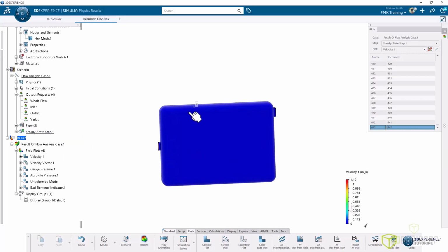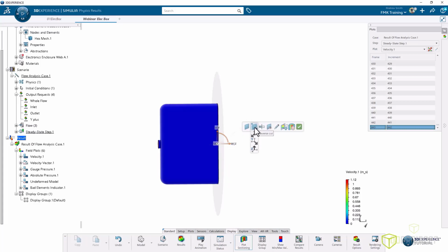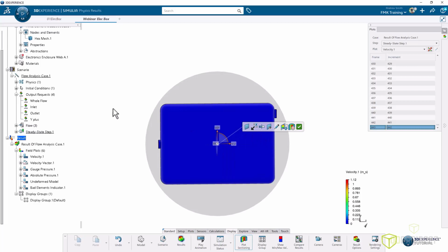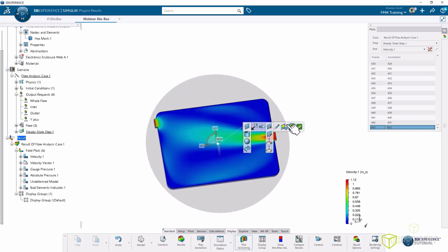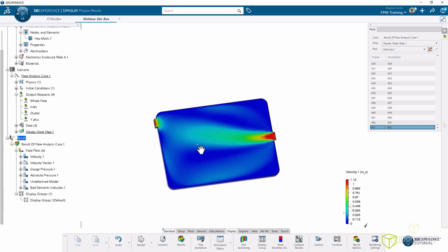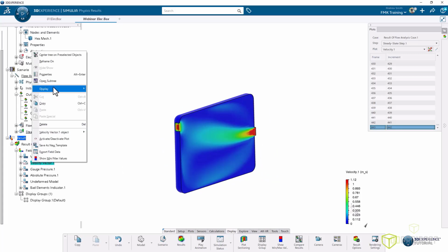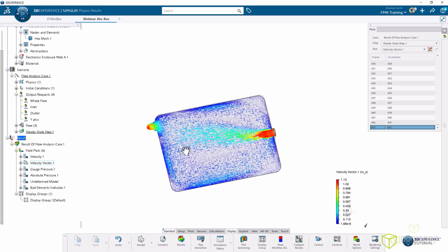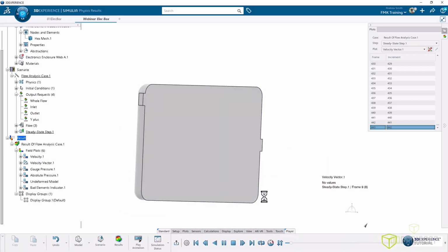Now this is obviously pretty boring because we have the no slip surface condition. If I want to look at the details, I go down here to display in the section tabs, plot sectioning, and I can choose the axis I want to cut normal to, and get some results. There's more details here we could talk about another time, but for now we'll leave that as is. You get the nice little plot here. I can also look at velocity vector plots, and I can also animate these plots.